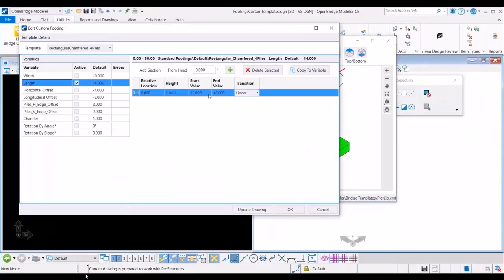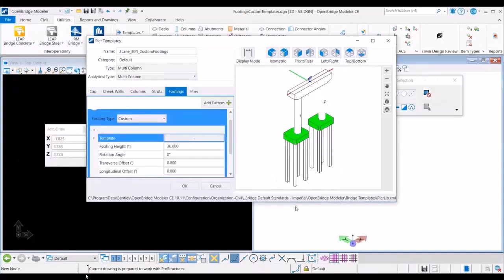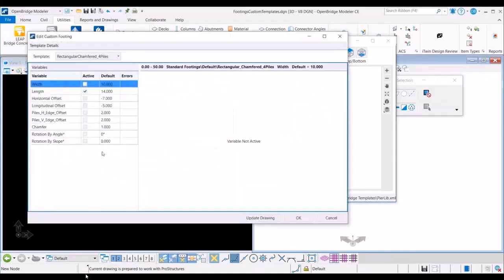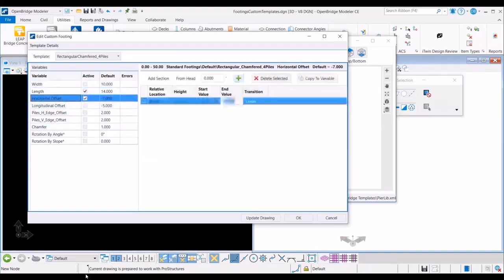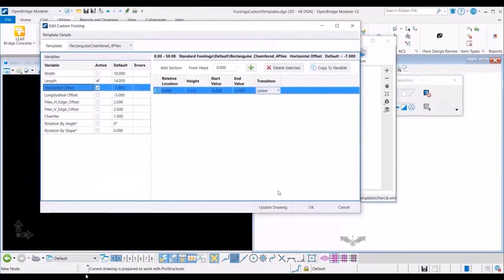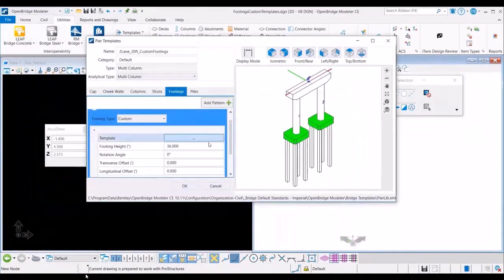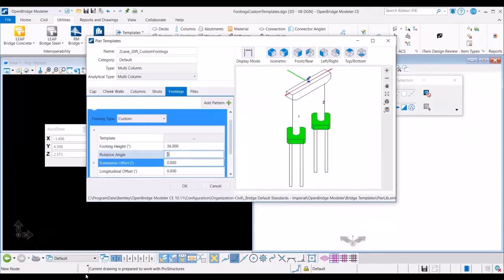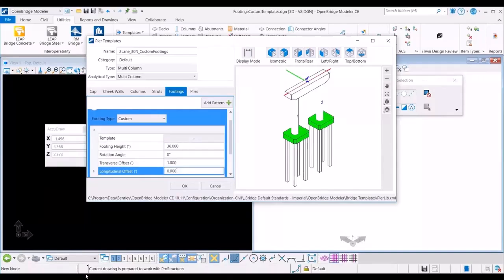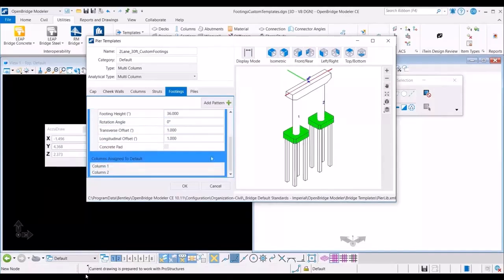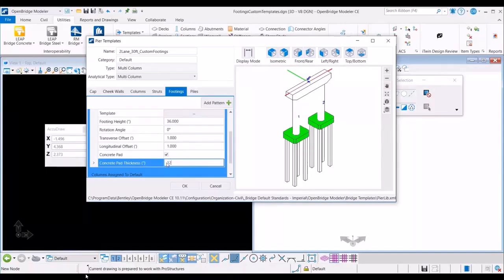So you can see, I can change the dimensions of the footing, change the dimensions of the spacing between the piles, and that's it. The height is given by the dialog box itself, right? And I just see the distances that I can define for the pile locations, right? And rotation too. So again, all of that is dialog box reading, as you can see, right? So control it like any other regular footing. The only difference is now it's a custom section.